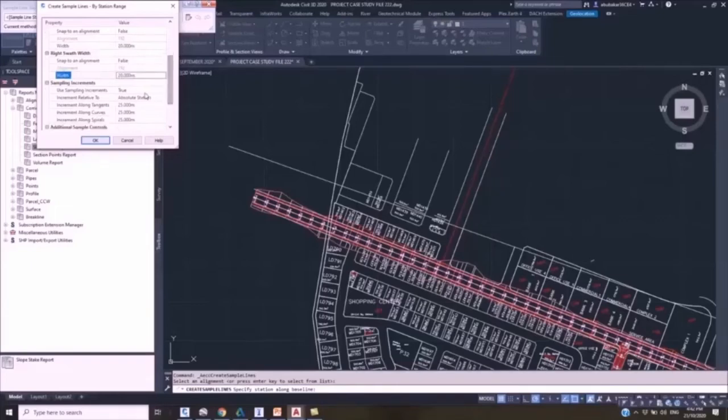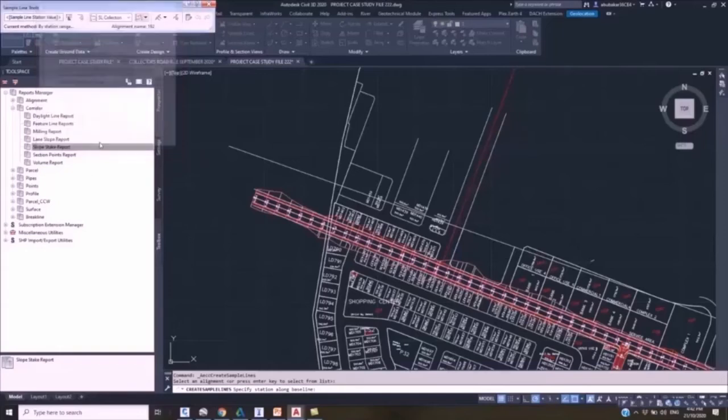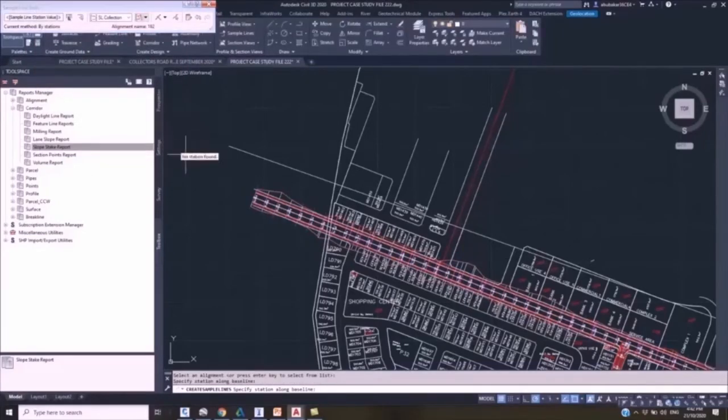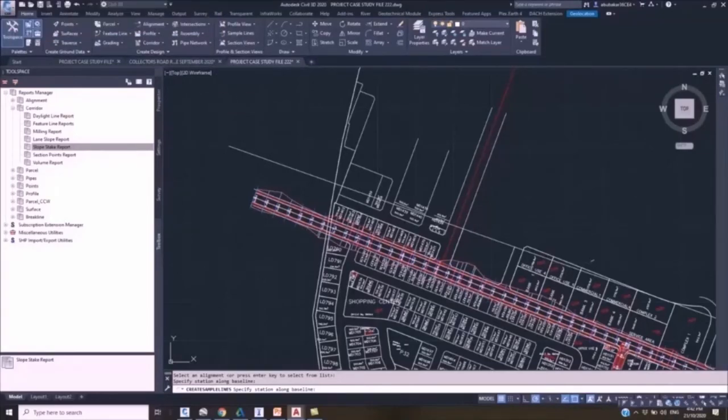Kindly note, the increment that we decide here for the alignment chainage interval is 20. So your tangent coordination for the increment in curves and in spiral must also be 20. So this is information that has already been input. I'm just doing some review for the design based on the information developed from InfraWorks to now reflect those changes to meet up with the design criteria expected. So from this, I've coordinated that.